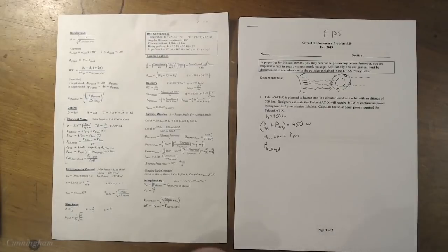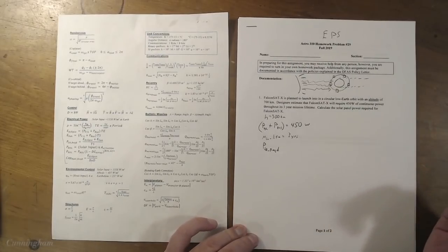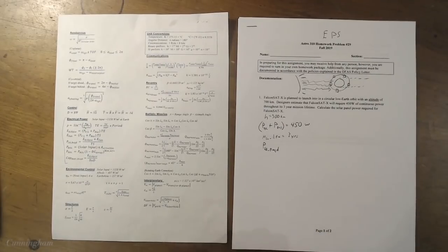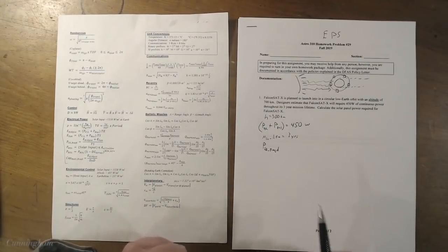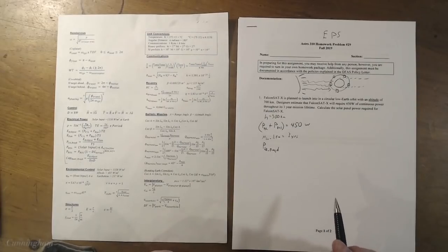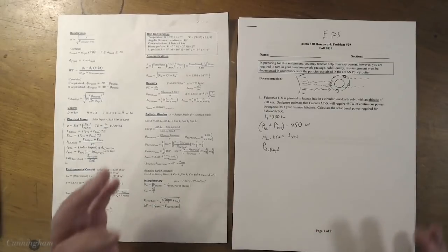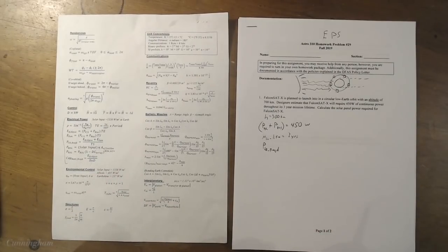And you might say, well, hey, weren't we just told that we need 450 watts of power and that's it? Isn't that the answer to number one here? And it's not quite the answer to number one. It's part of the problem. We need that much power to be powering the payload and the bus. But the trick is we need that much power during eclipse to be provided by the battery. So when we come out of eclipse, we need the solar panels to actually be a little bit bigger than you might imagine, because we have to not only run the payload and the bus in the sun, we have to charge up the battery for the next time we go into eclipse, right? So we actually need a little bit more solar power capacity than you might initially think.